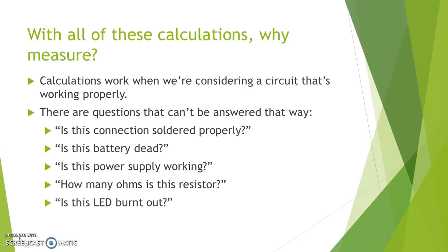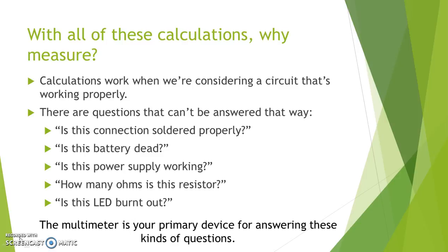We can also, with certain multimeters, answer a question about diodes. So some of them have diode testers, and since an LED is a diode, we can check to see if an LED is burnt out by using a specific kind of diode tester. Okay, all of these kinds of things can be answered using a multimeter, and because of its versatility, we tend to use it a great deal. We could design ways to test a lot of these things by building special circuits, but we don't need to because we've always got the multimeter handy.